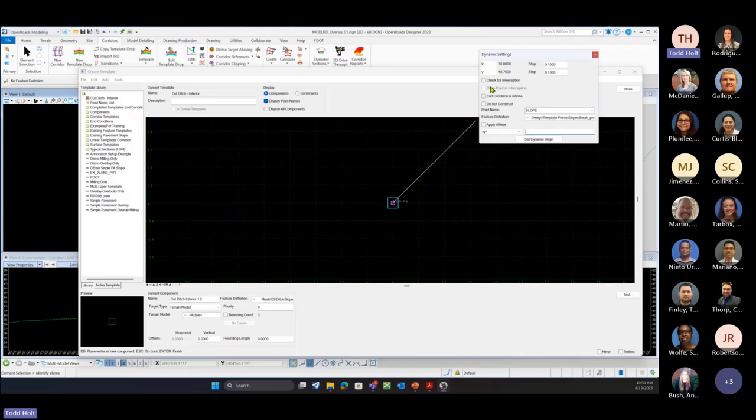We'll go through the different points, but we're going to leave all this off until the second last point and the last point that we place on there. And remember, if we have all these point properties turned off, it'll draw automatically for us. It'll always draw because it's finding that terrain.